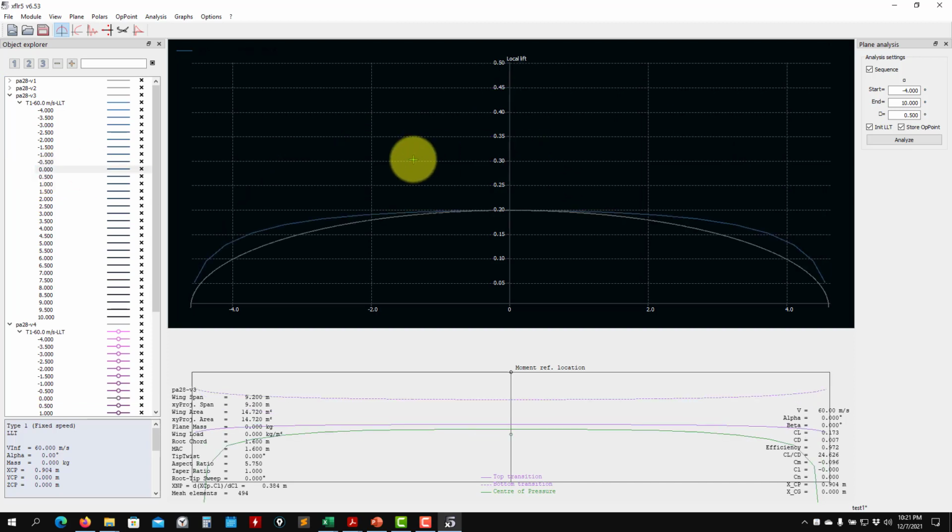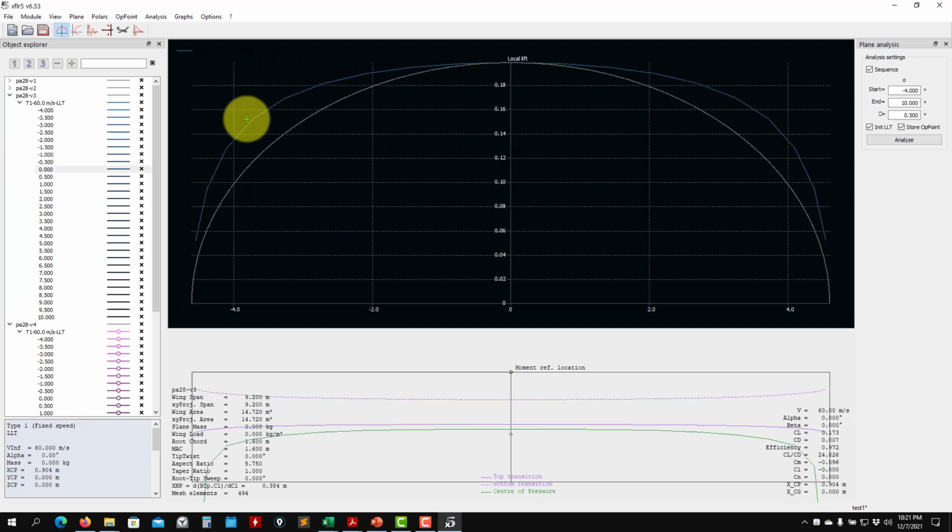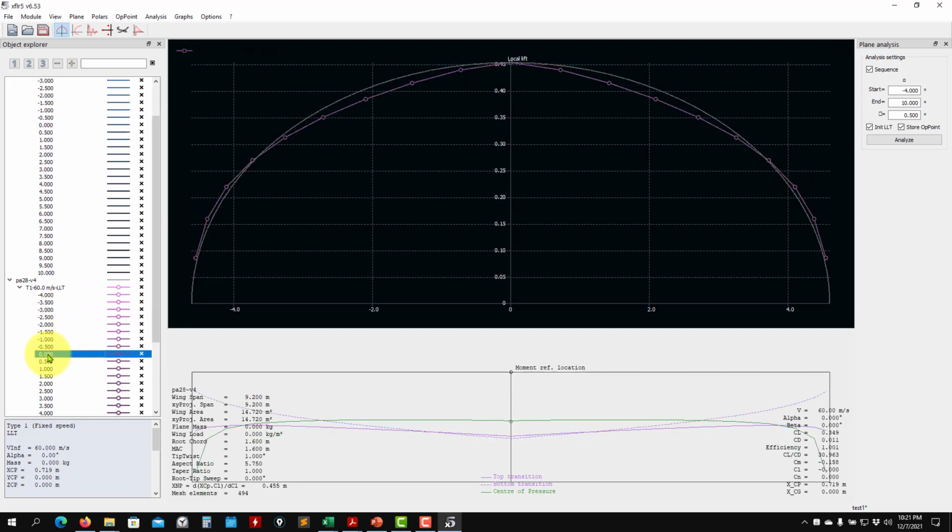See that in this case we have this problem here. This is a problem you are producing here. This is an excess of lift that you're producing, and this excess is responsible for the large induced drag. Instead, in this case, it is much lower. Here maybe we have a problem, but it's much better than the previous one. So this is already an optimal wing, this one that we have. We are producing the required lift, and we have the lower induced drag, very close to the elliptical lift distribution.